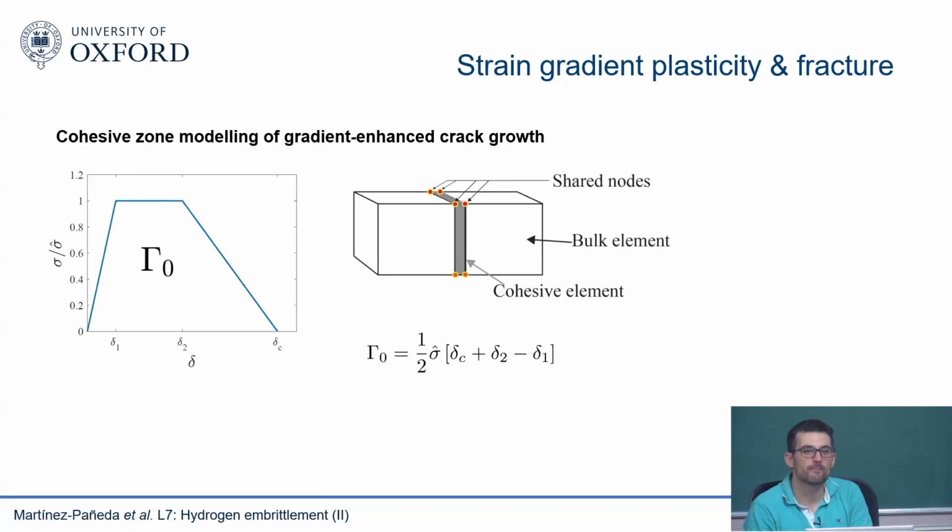In the case of ductile materials, generally we can see zones of localized strains. They call them strain localization bands. Generally within those bands, strain gradients are very high. And the width of those bands generally tends to be some microns. So is this length scale in some way related to the width of those bands?